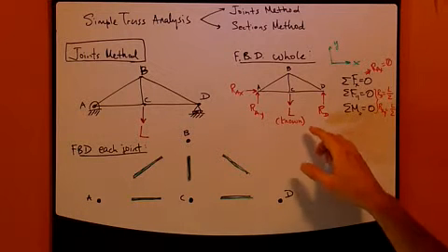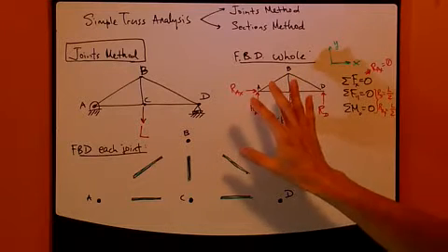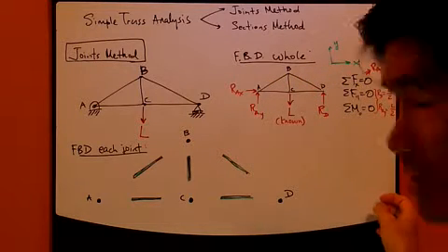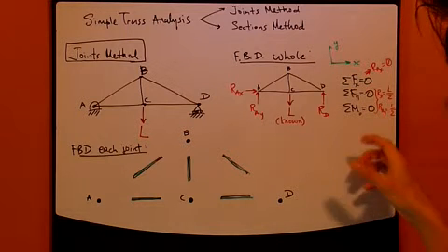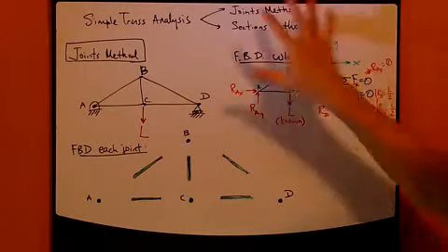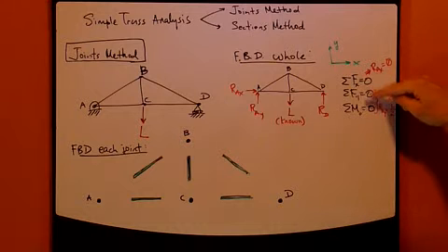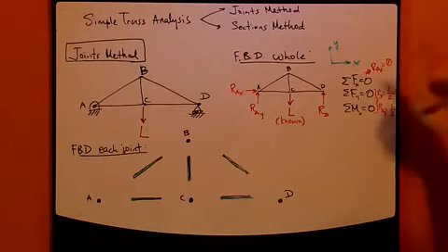So with this drawn, we can apply the equilibrium equations. This whole thing must be in equilibrium, so everything must cancel out. We have three equations in a two-dimensional space. The sum of forces equations, which are the X and Y components, are two equations.